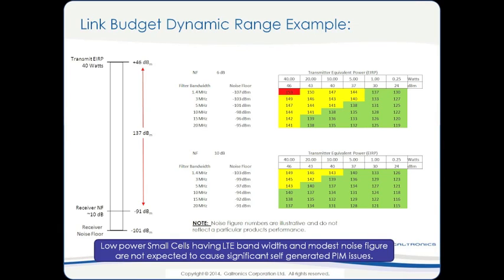What's included here, the red line is something that exceeds the 150 mark. If you add a 10 dB margin just to be safe, so 140 dB, I would still be concerned and still want to be using PIM certified, PIM compliant products.